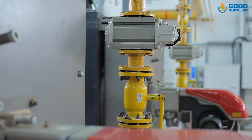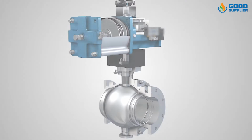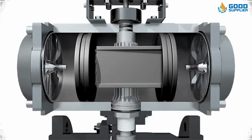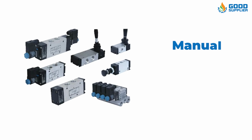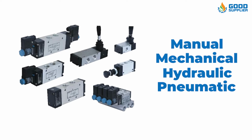The valves which are used in pneumatics mostly have a control function. This can be described as the operation of the valve in any process or the controlling of a quantity. A control function requires control energy. We could know the control energy by the mode of actuation. It can be manual, mechanical, hydraulic, or pneumatic.